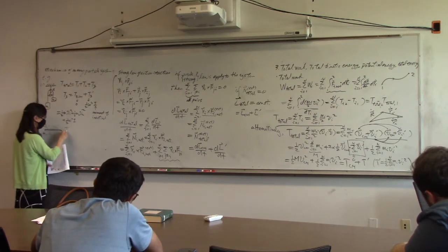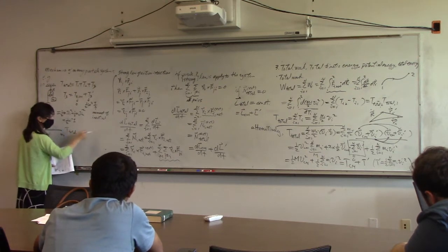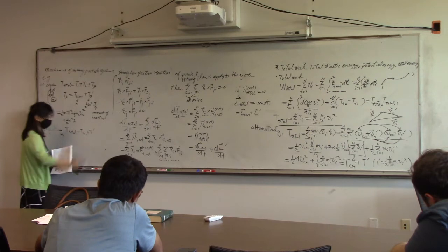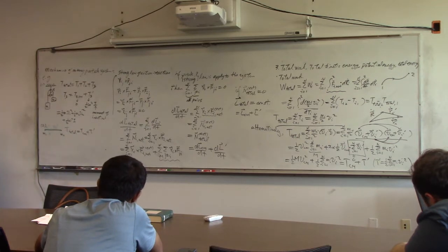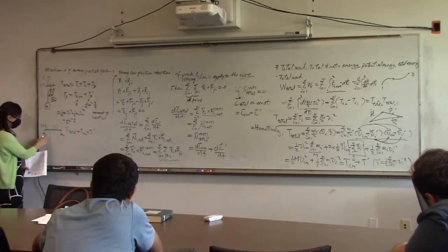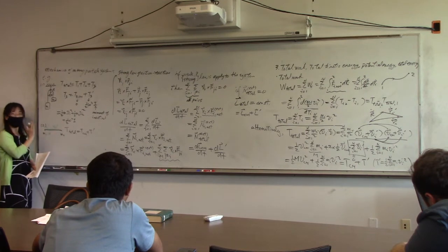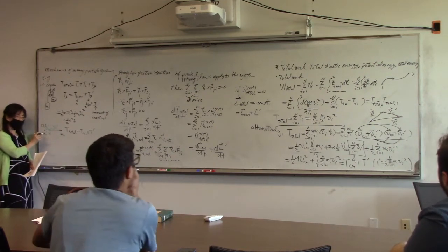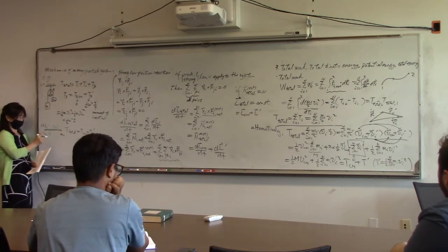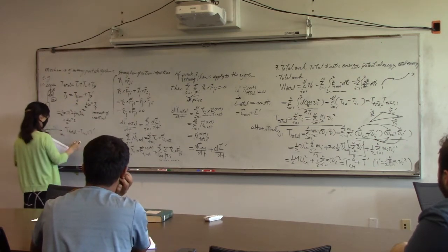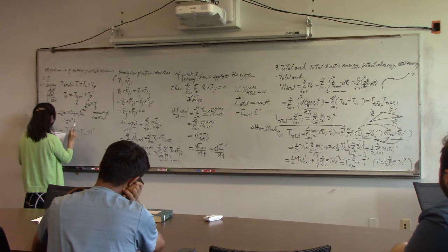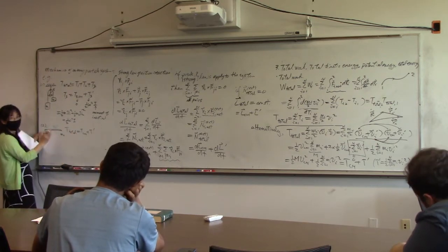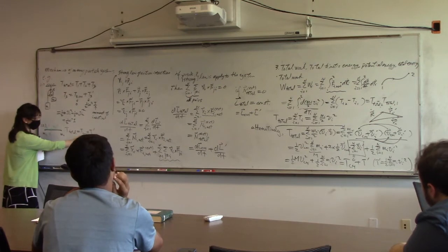So in this case, I prefer to use the second formula, the center of mass plus the relative kinetic energy, instead of the first. If you write the summation of the first it is also okay, but you need to find the coordinates such that you can calculate the absolute velocity. So in this case, I think that's enough. Depending on whether the center of mass changes, if not, this is 0, and only this one.